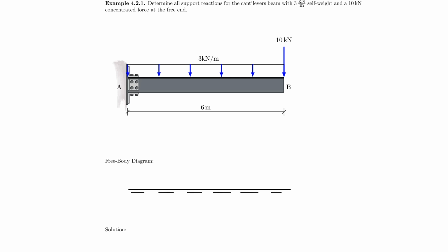You have to bring in the forces, and the forces that you have acting here are actually the vertical force, the horizontal force, and the rotation. So the forces would look something like that. And I just make an assumption here. I assume RAY to go in this direction, RAX in this direction, and MA about the z-axis to rotate clockwise.